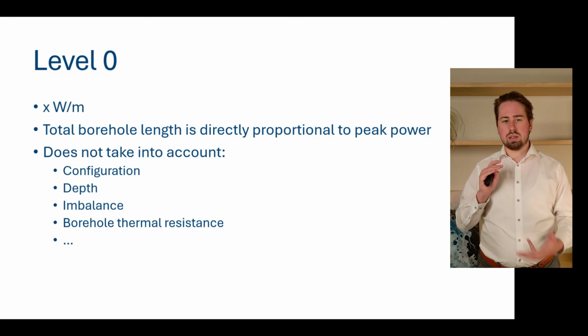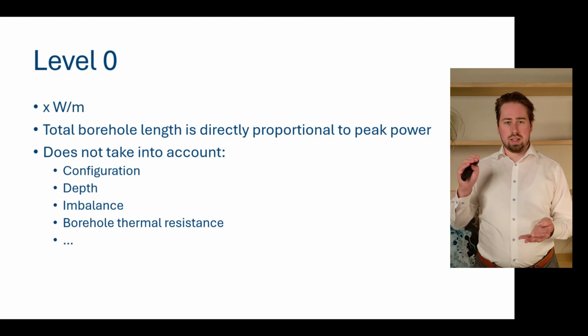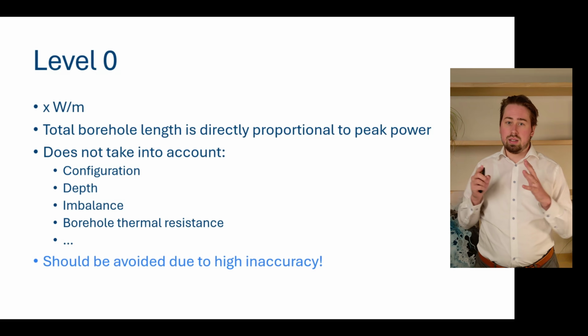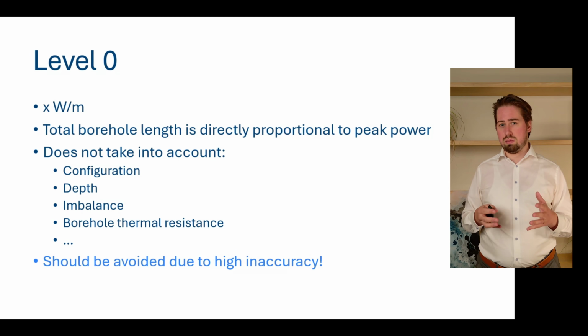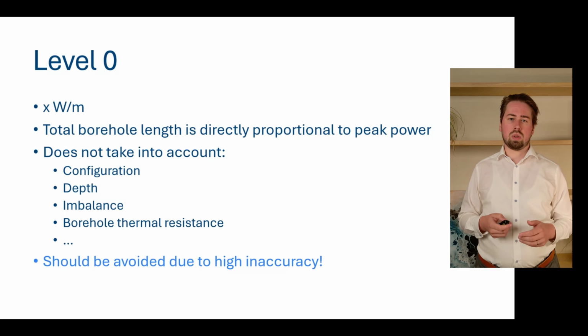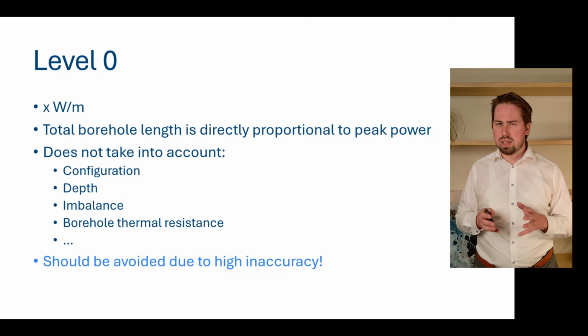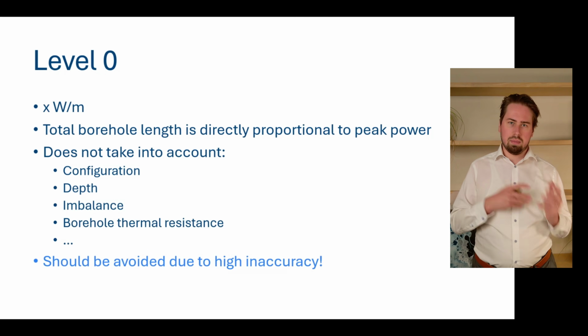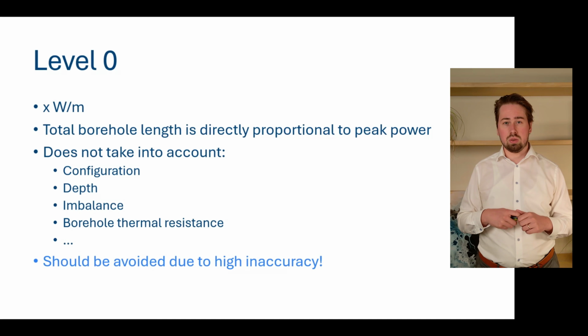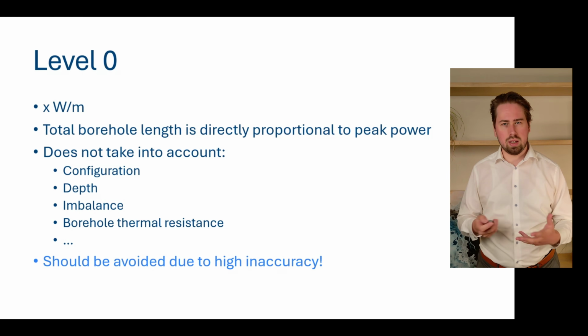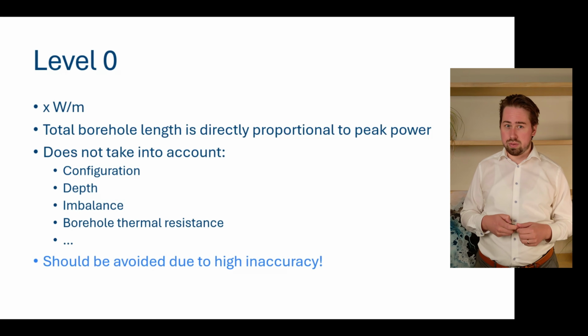It does not consider any imbalance. It does not consider the borehole thermal resistance. So basically it should be avoided when working with bore field sizing due to the very high inaccuracy. And basically we also covered this back in the first chapter when we were talking about, well, why should you follow this course? Why is bore field sizing important?